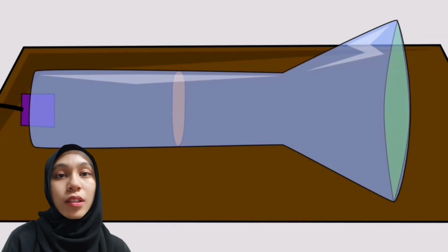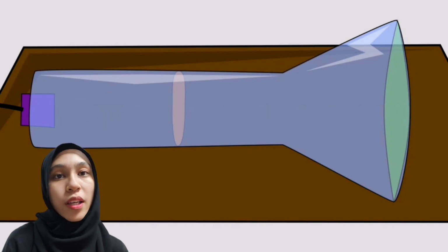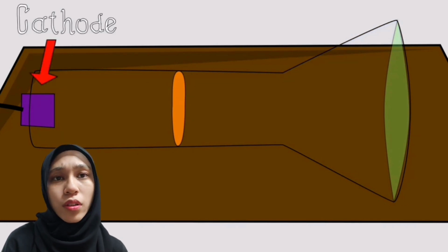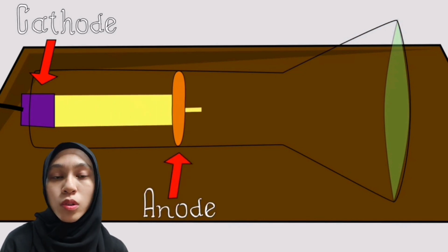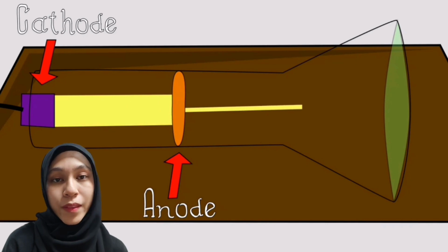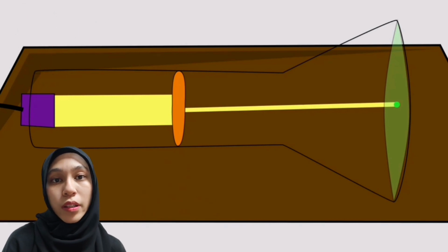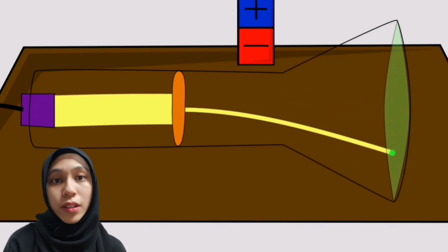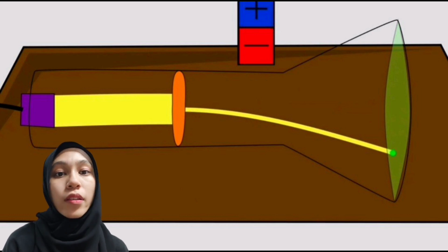Next, we proceed to how it works. A cathode ray tube is a glass vacuum tube that a beam of electrons is shot through, known as the cathode ray. The electrons are emitted from an electron gun. An electron gun is made of a cathode, which is heated to emit electrons, and an anode, which focuses the electrons into a thin beam. This beam easily travels through the vacuum and is illuminated by a screen coated in fluorescent substance. Since this beam has a negative charge, it can be affected by magnets, which are used to bend the beam. When done fast enough, an image can be displayed.